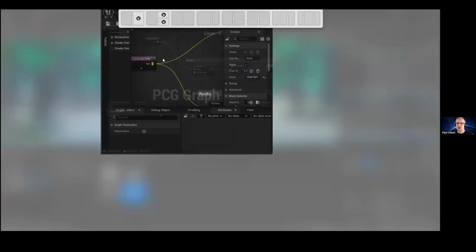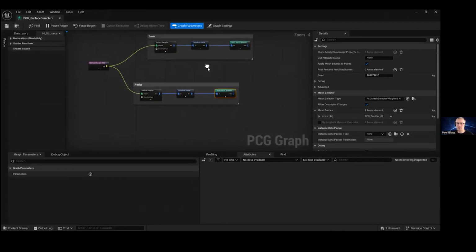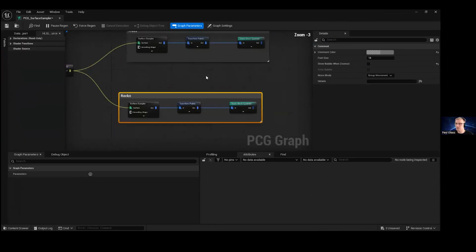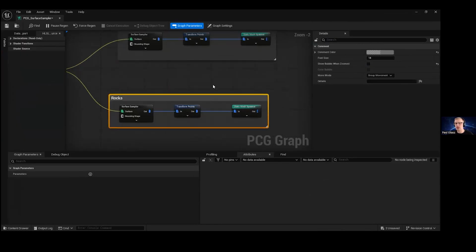And I'll show you how to do it. There's something called the difference node. What does it allow you to do? It makes the difference between what is already spawned, subtracting some of these points from the given node structure and then applying these missing points and replacing them with something new. So what it does is like a subtraction. It removes some of the points from the source and adds some points from the difference input node, and I'm going to show you how this really works.